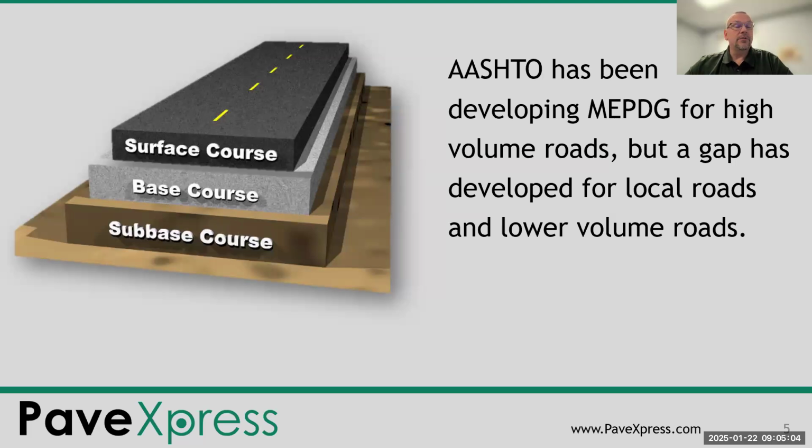While it improved the approach for designing high truck volume pavements for state DOTs, the practicality and applicability to local agencies and consultants for low volume road designs are questionable. Many agencies have long been comfortable with the 1993 AASHTO guide for design of pavement structures and the associated software known as Darwin. However, Darwin software is no longer available, and local agencies and consultants are faced with the lack of well-supported pavement design tools in the marketplace.